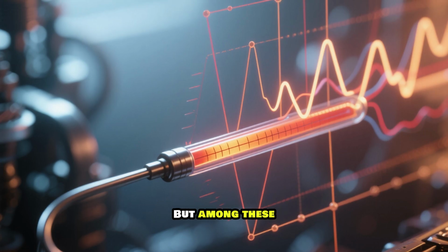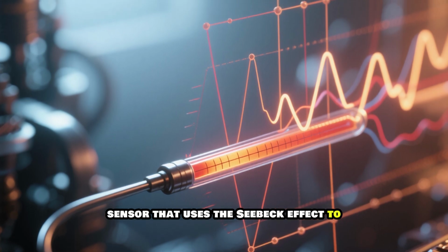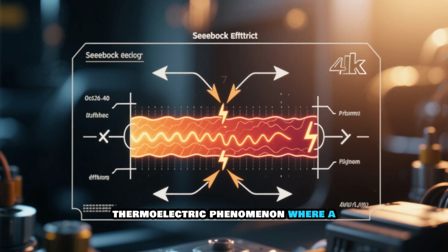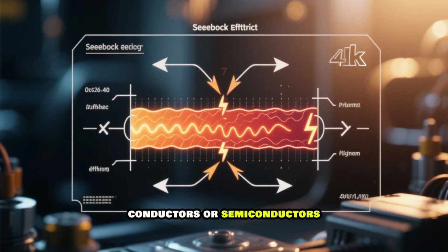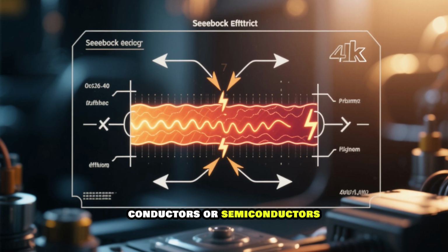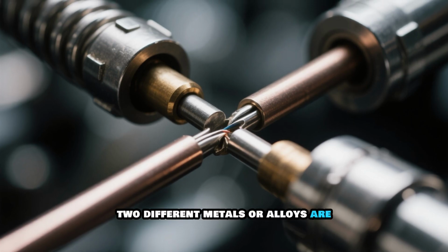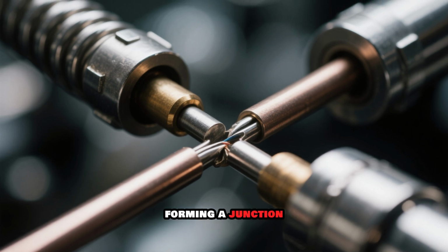But among these, a thermocouple is a temperature sensor that uses the Seebeck effect to measure temperature. The Seebeck effect is a thermoelectric phenomenon where a temperature difference between two dissimilar conductors or semiconductors generates a voltage. In a thermocouple, two different metals or alloys are joined together at one end, forming a junction.